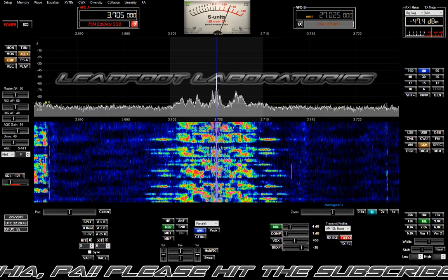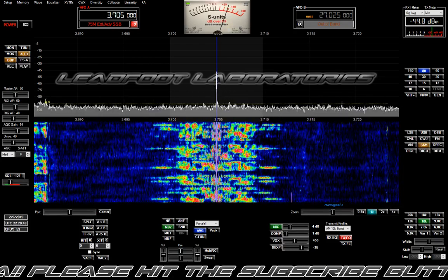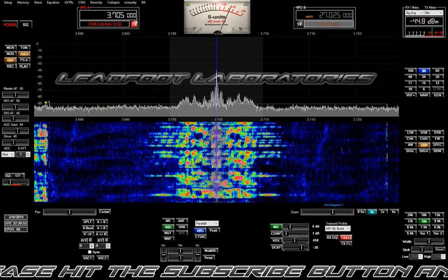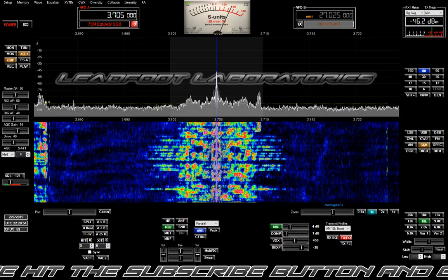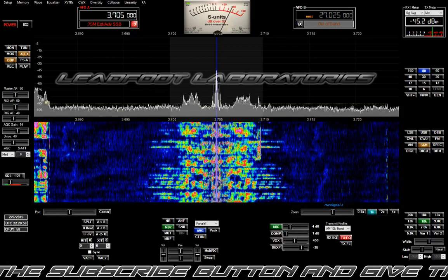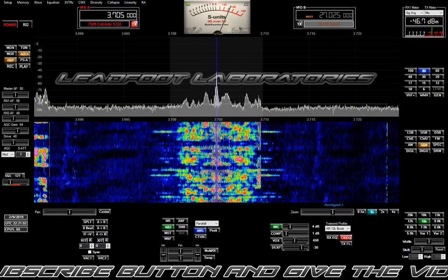I rely upon the asymmetric capability of the Inovonics 222. Let this thing go as high as it wants in the positive direction, which is actually up to about 130, 135% thereabouts. But only occasionally will I hit the 95% indicator on my mod monitor.